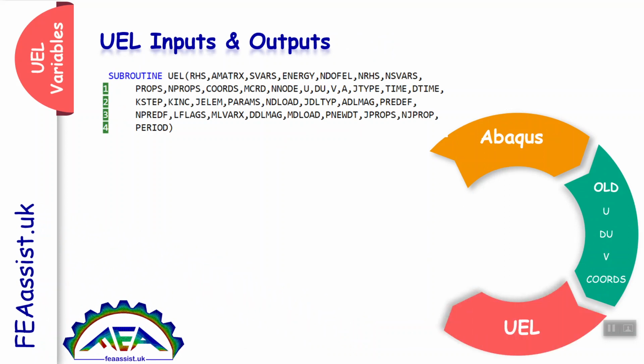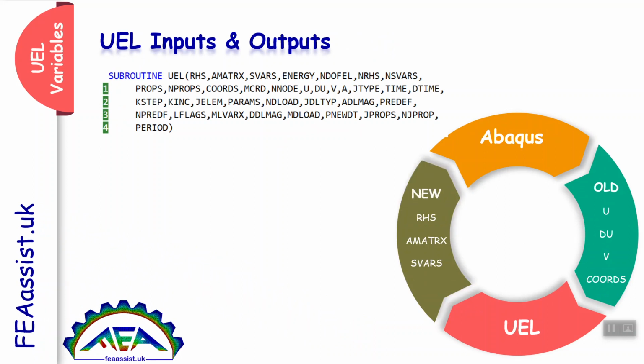We need to get these variables and define the interpolation matrix, interpolation function, and the element's force matrix and variables, and return these new variables back to Abaqus.